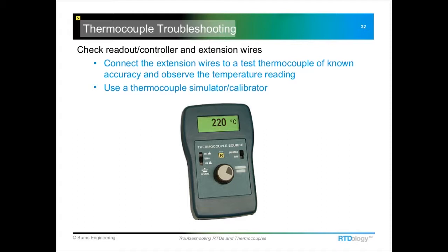Yeah, it could be thermocouples or RTDs. I classify them as, you've got the sensor errors and then you have the installation errors, and a lot of times the installation errors can be a lot larger than the temperature probe errors. So you can have a temperature probe calibrate fine in the bath, throw it in the process, and it's not going to read right. And it's because you've got some stem conduction or some other issues with how the probe is installed into the process.